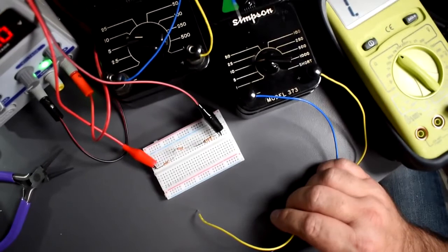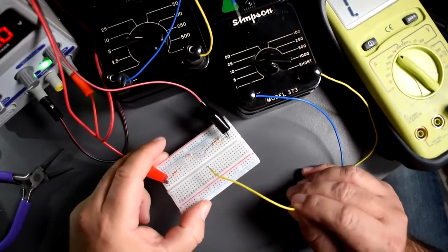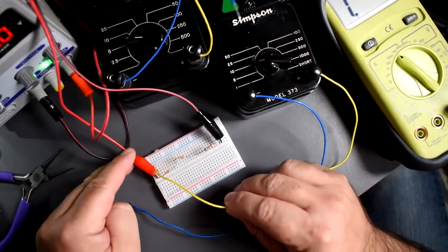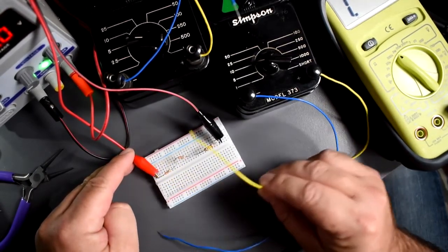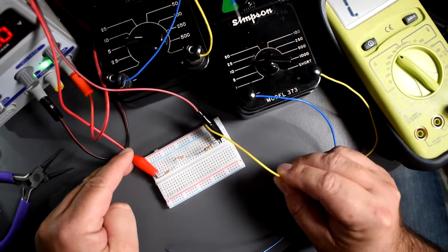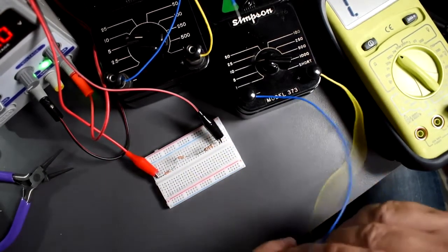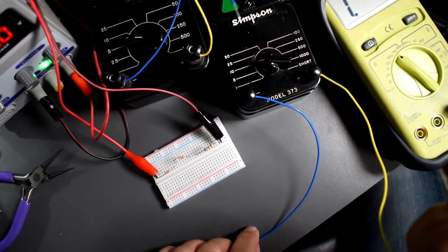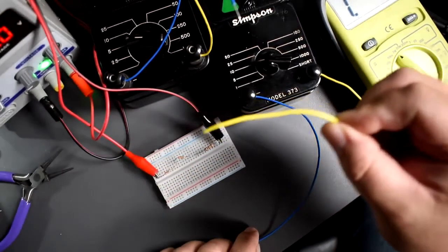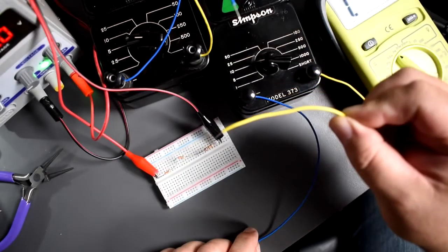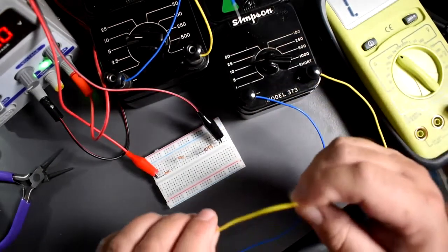All right, we have broken the circuit right here. So we're going to connect, okay, here's a positive, here's a negative terminal of the power supply. So how are we going to polarize this meter? We're going to polarize this meter so the positive goes to the positive side, and then the negative goes to the more negative side of this circuit.